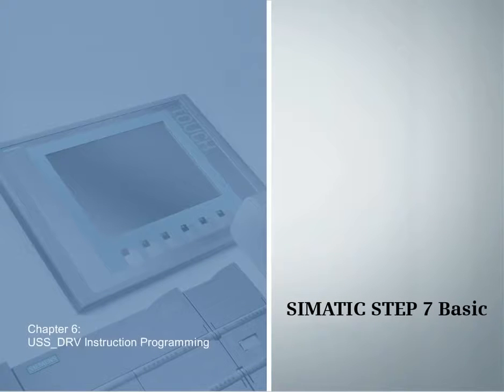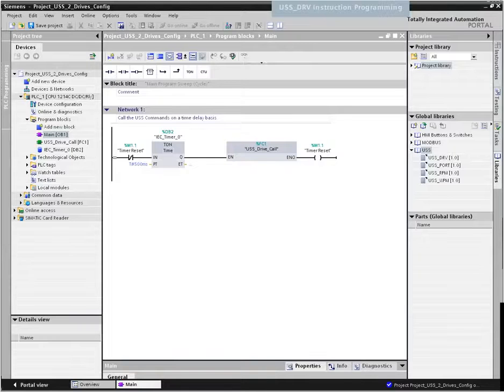Chapter 6. Call and configuration of the USS drive function block. Only call the USS drive FB in the main OB1. We use a TON timer, on delay, with a delay of 500 milliseconds to guarantee the consistent updating of drive states. In this example, the USS drive call function contains two USS drive calls. Below, we look at how to configure these drive calls.